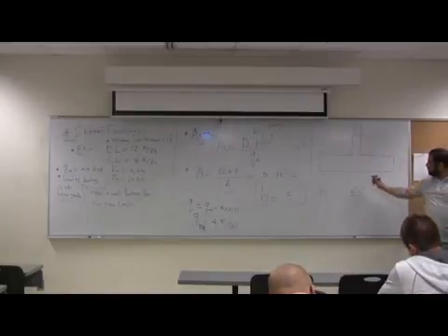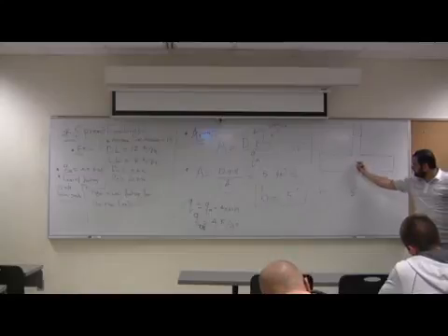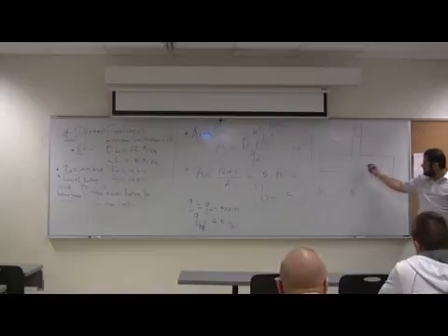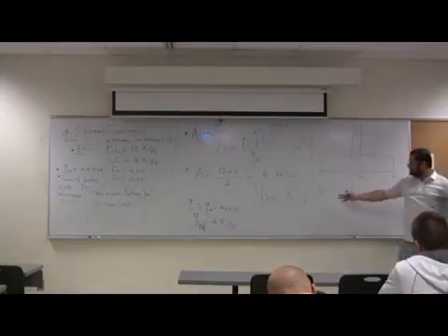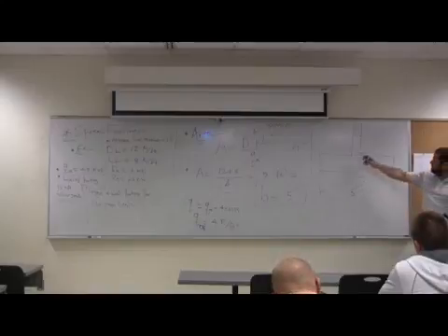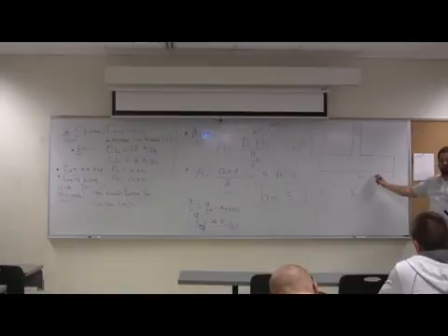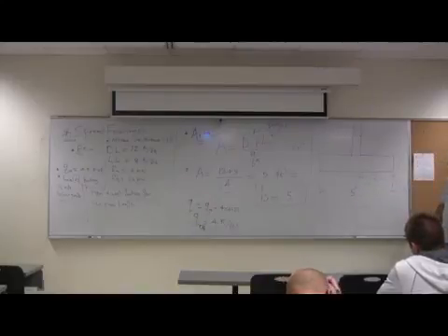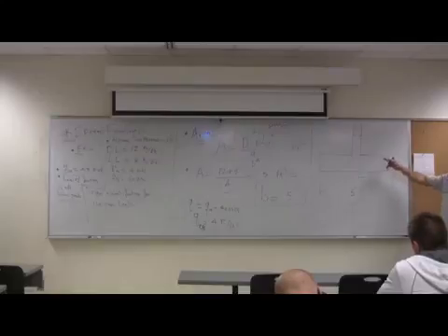Okay? So what's this distance from here to here? This cantilever, how is it 1.5? All of it is 5. To the center is 2.5. Right? So this is 2.5 minus half, okay, guys? 2. That's the cantilever length.